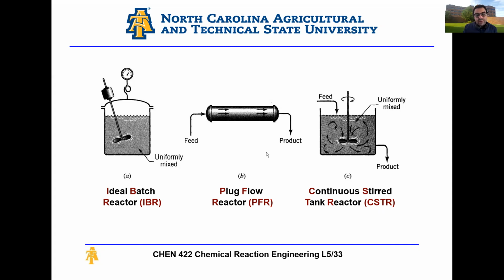A plug flow reactor and a CSTR are both continuous systems, right? And by continuous systems, it means that the reaction is happening along with the flow. So the feed enters this reactor, you might have a catalyst, you might have some other arrangement in there, and then it reacts while it's passing through and I get the product. And in the CSTR, the feed enters my basically fluid basin, I have a mixer, and then I get the product, okay? These two continuous, this guy non-continuous.